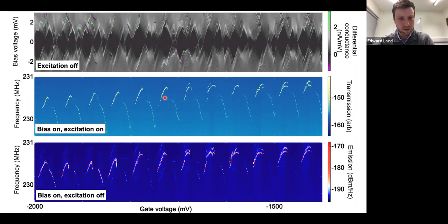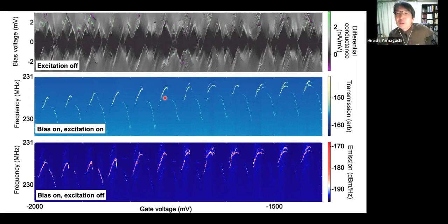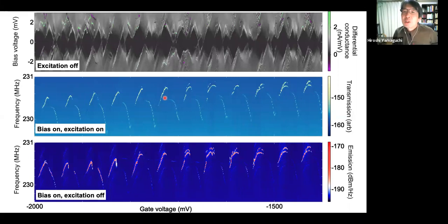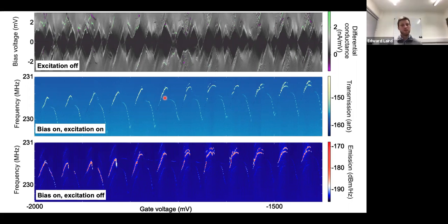Okay, one question from the audience. Thanks for an exceptional talk, Edward. In one slide, you show the device with the 5 gates, which is the piece of the gate electrodes and the pitches among each other onto source and drain. Are they deposited in the same step? So asking about the fabrication, I think. Oh, no, they have to be deposited in separate steps because the contacts have to be thicker than the gate electrodes. Otherwise, the nanotube won't suspend.